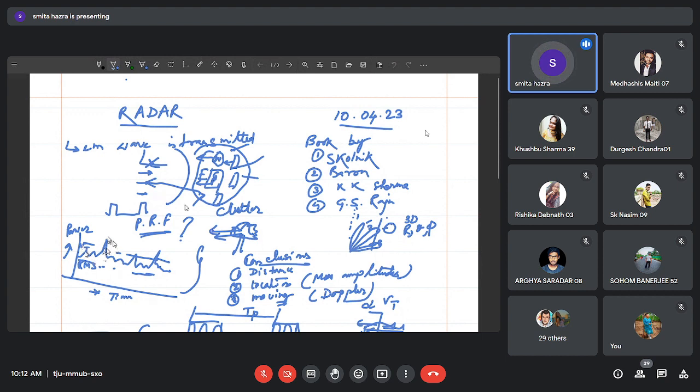And its simultaneous effect: to stop that, that means to make the probability of the false alarm lower, what we can do is make VT a sufficiently high level, that means the threshold. So then what will happen if there is a real object and it is giving a very small scattering cross section? I mean the sigma value becomes very small.